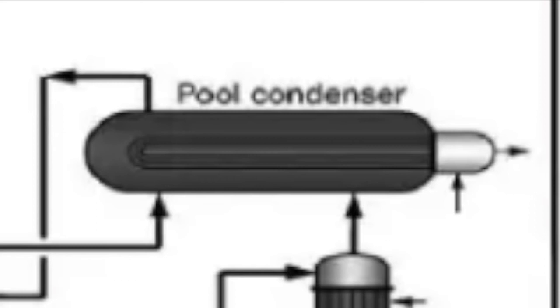The pool condenser is a horizontal vessel with a U-tube bundle submerged in it. Within the tubes of the heat exchanger, low-pressure steam is generated. This equipment combines the functions of a conventional falling film type carbamate condenser and a urea reactor. Thus, the reactor volume can be decreased by about 30 to 40% compared to conventional processes.